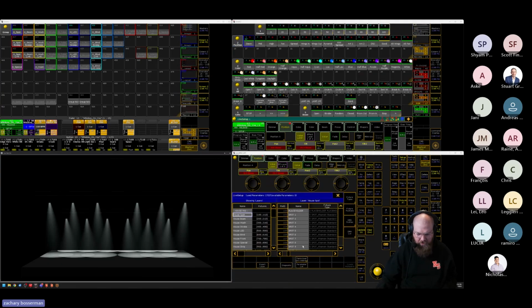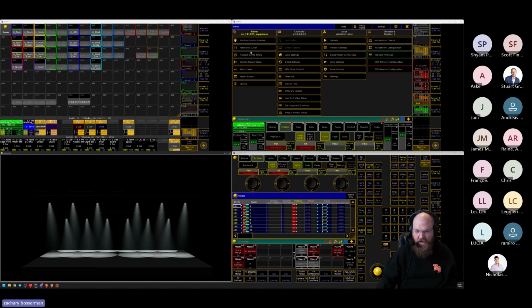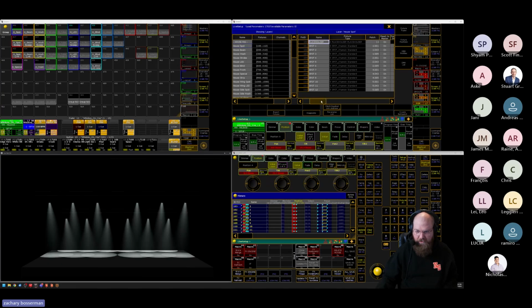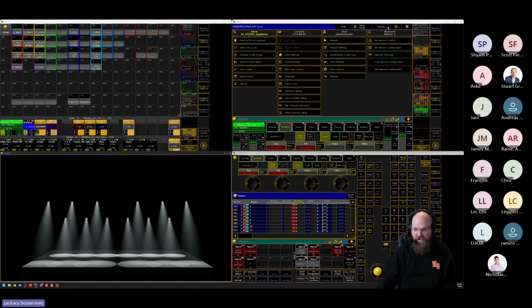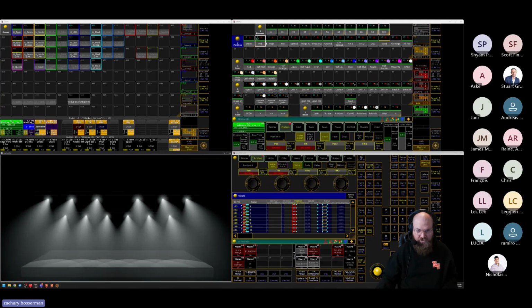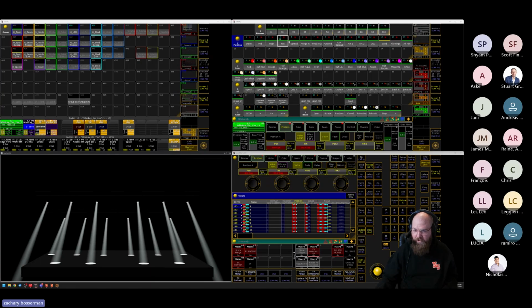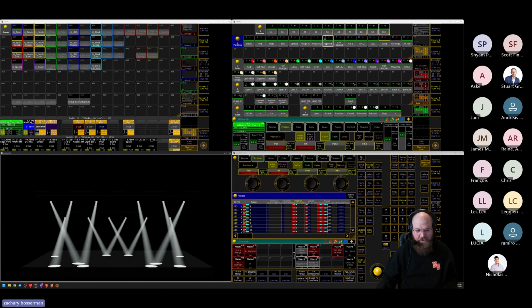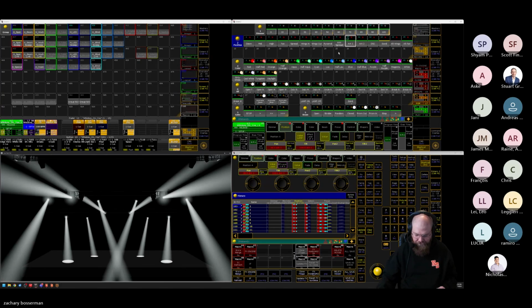In our patch only mode, I'm going to shift over. Let me pop this up so you guys can see a little better. There we go. We're up high. I'm going to grab these spots and I'm going to invert my DMX. I'm going to hit yes. And then you saw down here, they all kind of tilted out the right way. Now, if I go through and check my positions, we'll get this a little tighter so we can see. They're all pointing the ways they're supposed to. Wings in, pyramid, all my positions that I use day to day on my show are going to look correct.